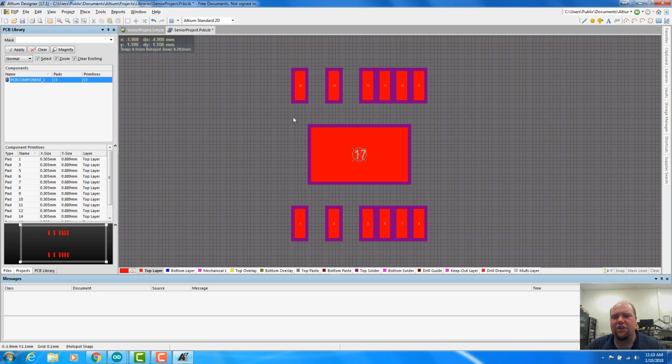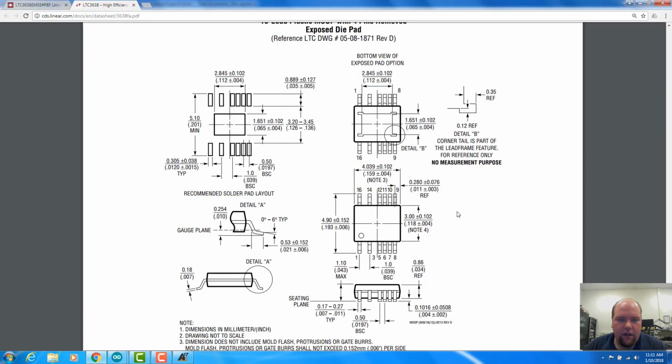Sometimes I also like to just put an outline of the part so that when I have my PCB and there's no parts yet on the PCB, I can still generally see where those parts connect, especially for a high density board. Sometimes just looking at it can be tough to see where those center bodies of components are. So I'll do both just for fun here. So let's go back to this. Let's put a little silkscreen that shows the outline and a silkscreen that does pin 1.